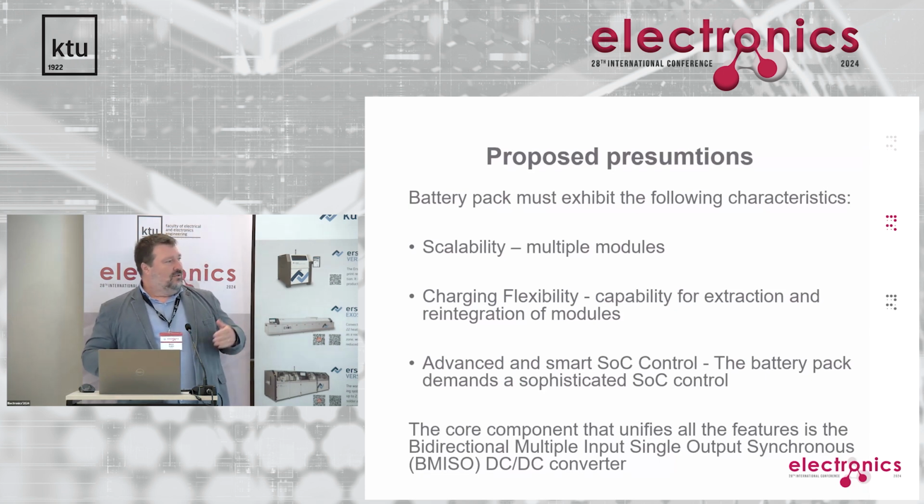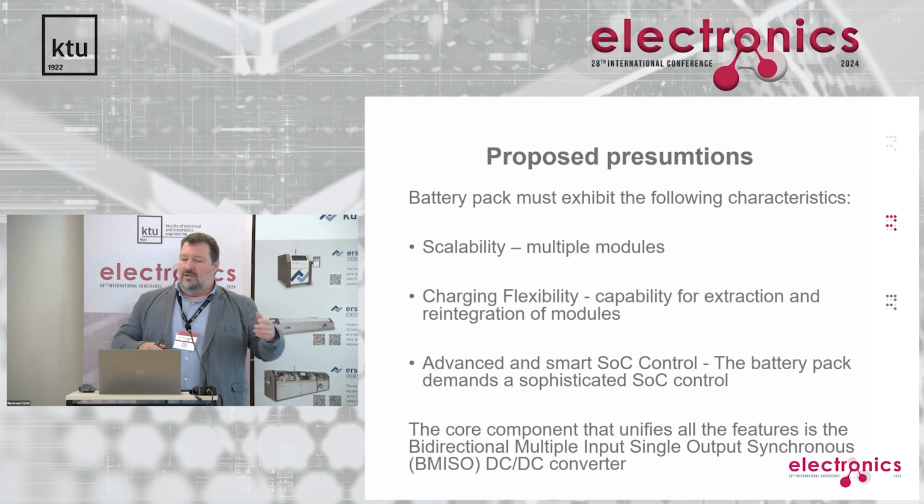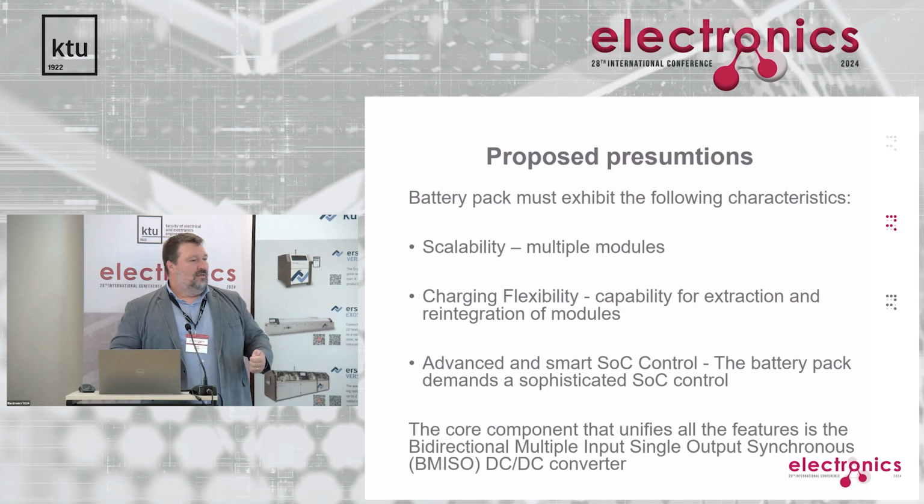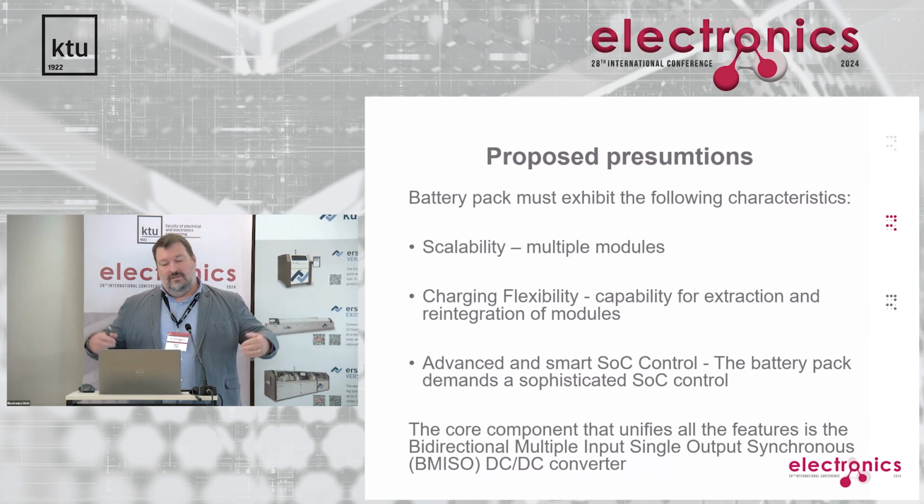Since all those modules are in parallel, it's obvious that the total voltage of the system is the voltage of one module. And when you need to extend capacity of this system, then you add additional modules to the battery pack.